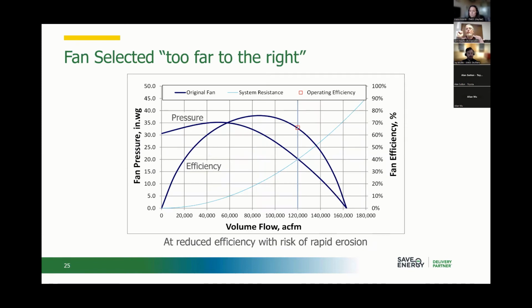Okay, one more I want to show you here. This one is something called an axial fan, which is a completely different fan. One of our guys in our office made this little mock-up, and it did a pretty nice job of duplicating a scale model of a real mine ventilation fan. This kind of fan behaves differently. With the other ones, the flow comes in and goes out at 90 degrees. But you know what? You can select this kind of fan and also achieve efficiencies in the 85% range. I'm going to hold that thought though, because the next slide, I'm going to make that point.